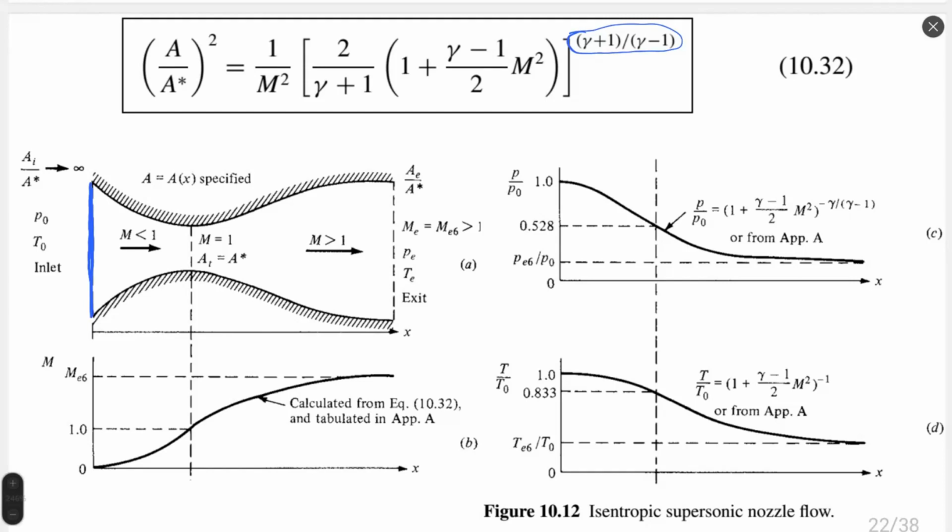And for this cross section, I will say that it's approximately 3 times bigger than throat. So this section 1 would be A1 divided by A asterisk, relative area, is 3. Okay, and let me calculate in same section, but in supersonic part. This is section 2.